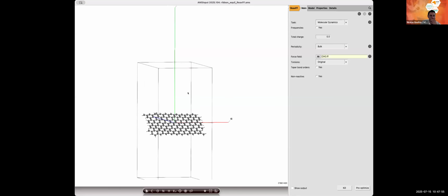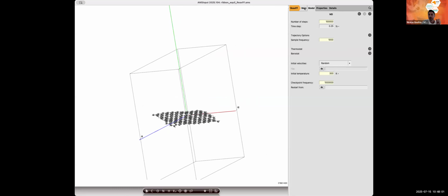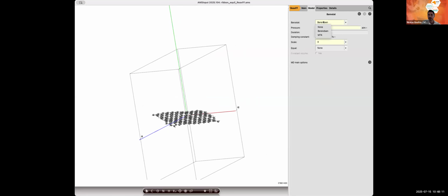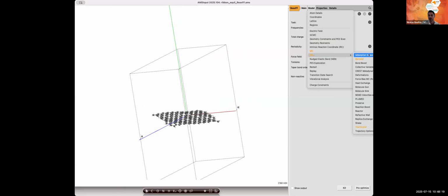All right, so now it's equilibrated. It's a little bit tilted, but it's okay. I'm just going to add the deformation, and we run that, and then we'll get to the result. So I'll run it a bit longer. Maybe I can also remove the barostat, right? I don't need the barostat. I'm going to do the deformation just in NPT, basically, just with a thermostat.